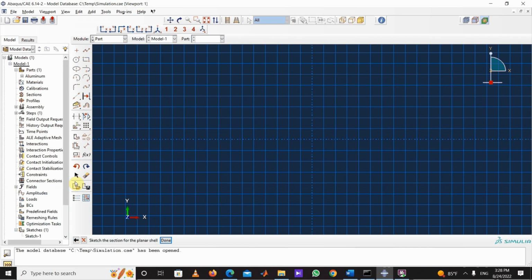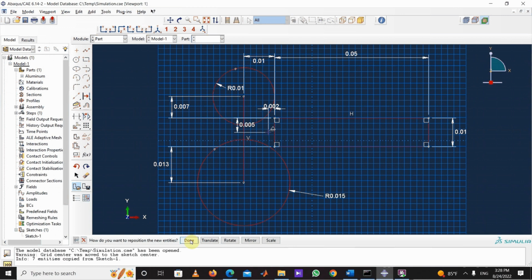Okay. I click on Add Sketch, select the sketch and press Done, and as I mentioned earlier, I should convert the redundant geometries into construction. So I hold down the Shift key for selecting the redundant geometry, multiple geometries, and finally I click on that.